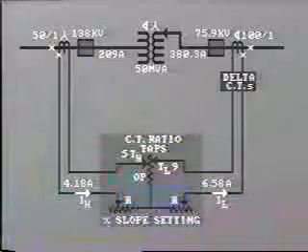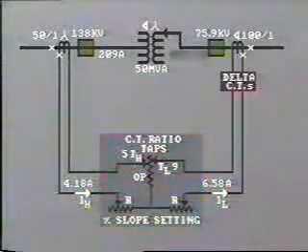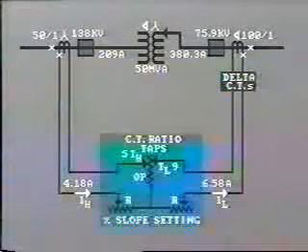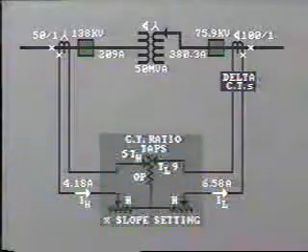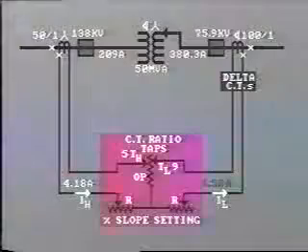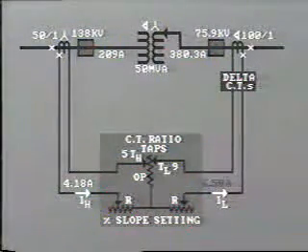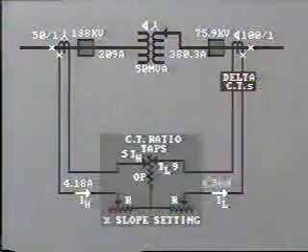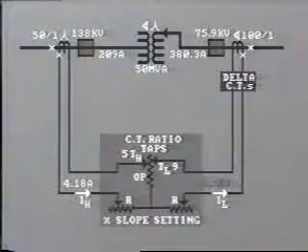The line current in the secondary would now be 50,000 divided by root 3 times 75.9, which equals 380.3 amps. The secondary current in the restraint winding would now be 380.3 divided by 100 times root 3, or 6.58 amps.